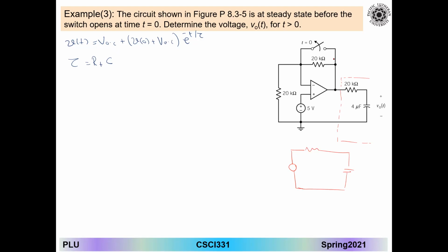Since this part is separate from the other circuit, using all the other elements I end up with the voltage at this particular point. That's exactly what I am looking for from the entire part on the left side of my capacitor. Here is what we call V open circuit, or whatever name you want to call it.